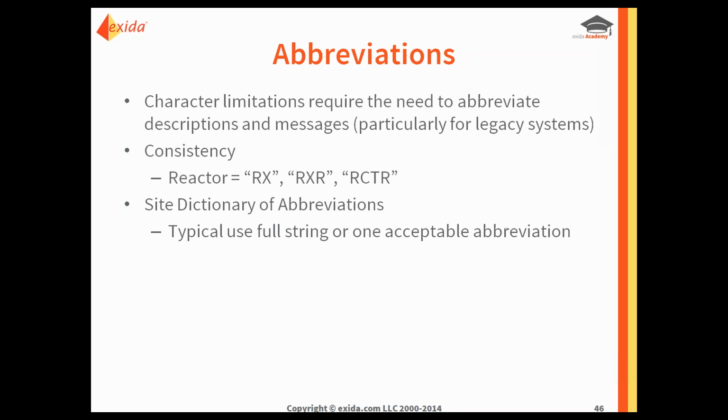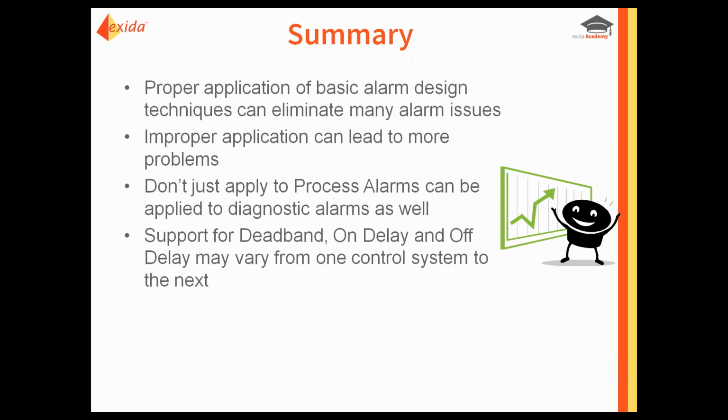And that can be incredibly confusing to the operators, particularly newer operators or operators that are transitioning from one unit to another. So it's definitely something to try to clean up during rationalization or during basic alarm design, and to make sure that you're defining some acceptable abbreviations, and then either using that abbreviation or the full text string. That's the recommendation.